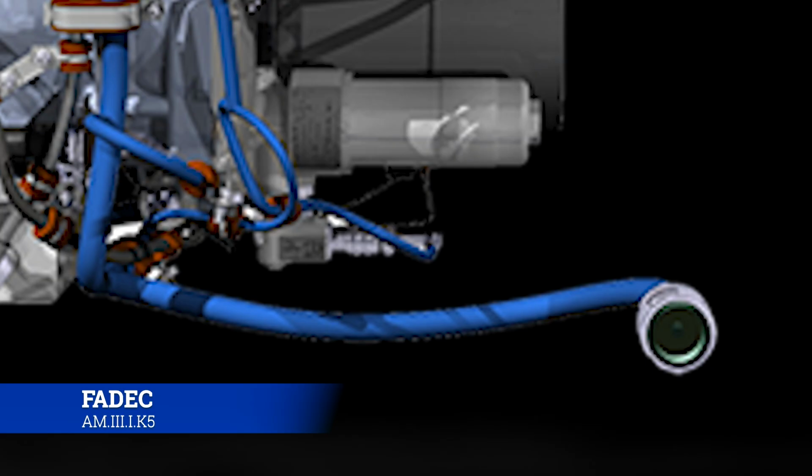And so it's going to add fuel or take away fuel based on whatever is going on to try to optimize that fuel flow to make sure the engine RPM stays exactly where it's supposed to be. It's a pretty awesome system, and once you've flown with FADEC, you'll only ever want to fly with FADEC because it takes so much work off of the pilot themselves. But the main difference for your test and everything that you're going to want to know is that FADEC is just full authority digital engine control, and there are no mechanical linkages like with the hydromechanical unit that has electronic fuel control attached to it. That's going to be the big difference.